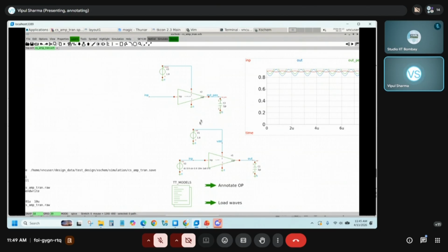So this I have done, but the only thing which has changed is the name of this output net, because now the result for my upper test bench schematic will be run on post layout netlist, PEX netlist. So I want to separate these nodes, and I want to compare what my output results are when I run the same simulation under same circumstances on these two separate test benches, one with front end ideal netlist and another one with post layout netlist.